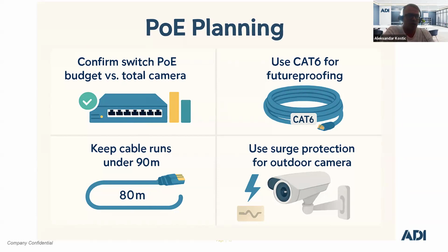When we speak about surge protection, it is related to the type of cabling used, in order to have different parts of the network isolated from that same voltage level. So, for example, in my CCTV design, I have two buildings, and those two buildings were connected through a fiber optical link. That fiber optical link provides perfect isolation.